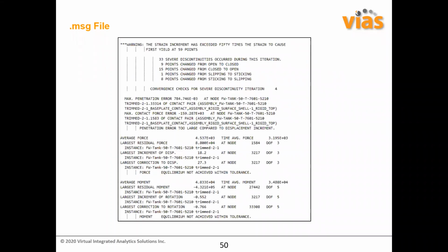In the .msg file, which is openable by a standard text editor, you need to take a look at the average force. Remember that we talked about that green curve, load versus displacement. The average force is computed within Abaqus from the model, which is the resultant, you can say, on the elements of the applied force at that section.